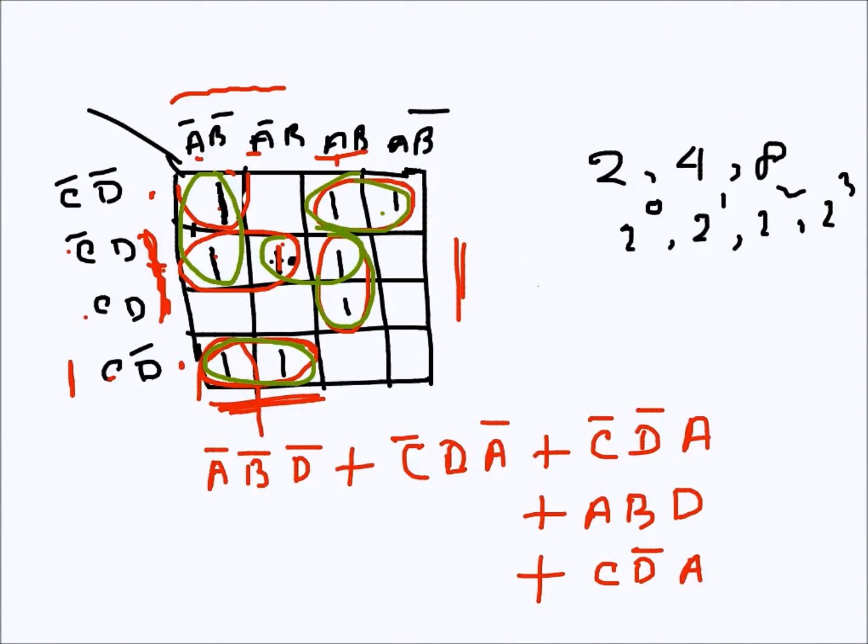So we could have ended up with a different expression, that's fine, but basically by minimization we mean how many AND gates and OR gates we are needing, and that would be the same whichever way we group them. We can get different expressions, but the number of AND terms and number of OR terms will be the same if it is minimized properly.